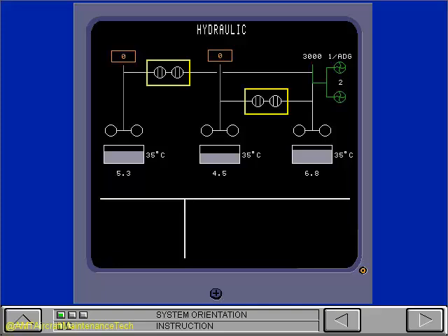Reversible motor pumps, or RMPs, are off when the double valve symbols are closed. The closed indication shows the valve symbols perpendicular to the schematic line. With the RMPs on and the system at 2400 psi for 2 seconds, the valve symbols become green and the double lines show parallel to the schematic line.